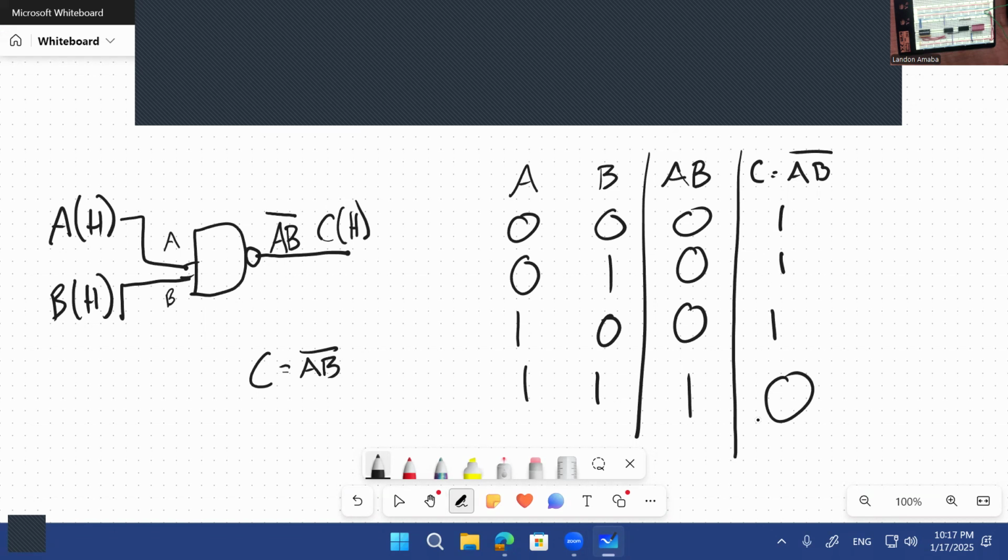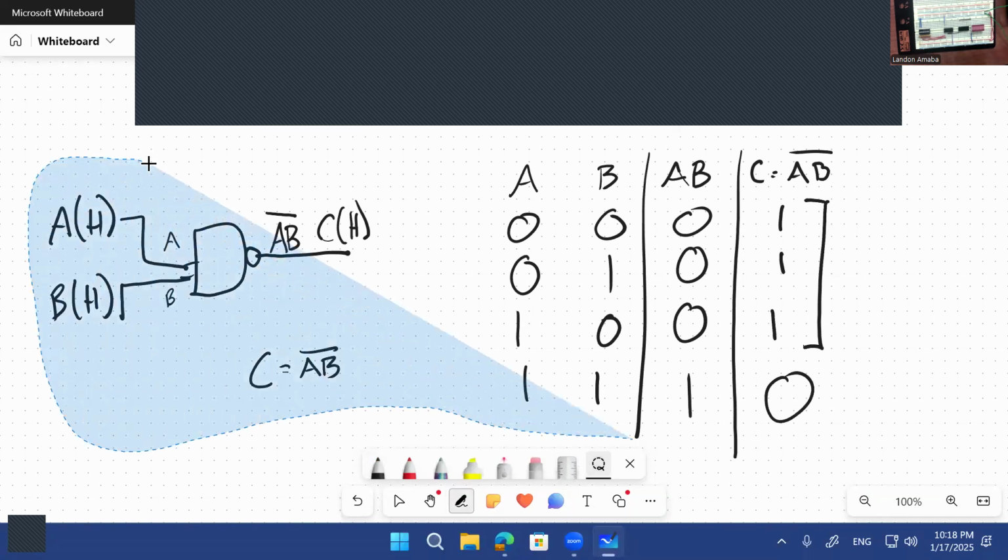So what this tells us is that we're sending a true signal into our active high LED in every combination except for this last one. Okay, so now this kind of explains why in every configuration the light is on, but then in our last configuration it's actually off. Okay, so when you're dealing with these switch and LED circuits, it's important to note these activation levels.